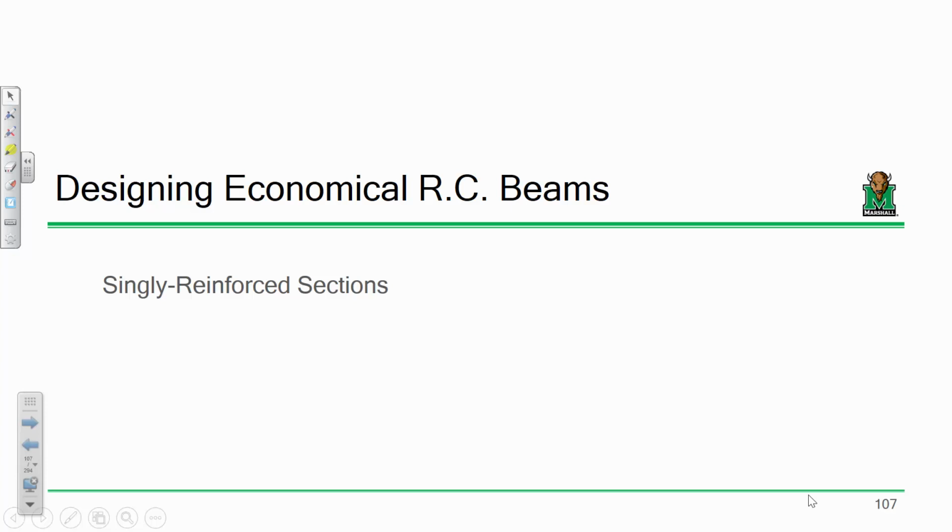But rho is what's called a reinforcement ratio. The way that you compute it is you take the area of steel and you divide it by b times d. But what it really is, is sort of a percentage of reinforcement. In other words, you take the area of steel divided by what I guess you would call the effective area of the concrete.